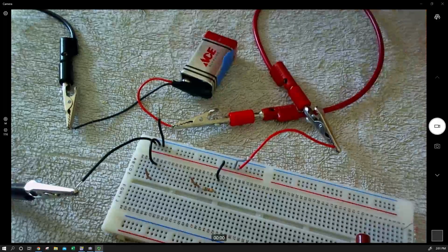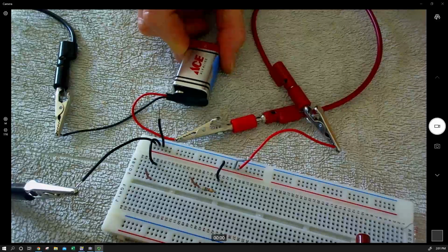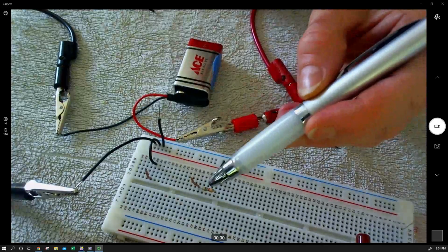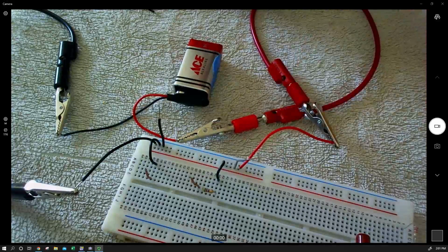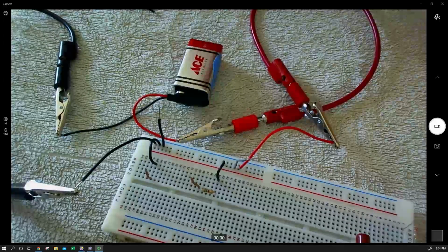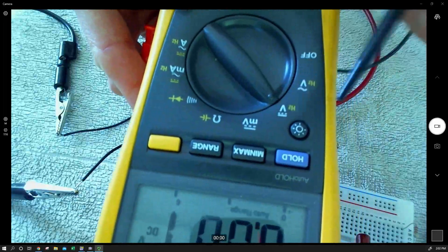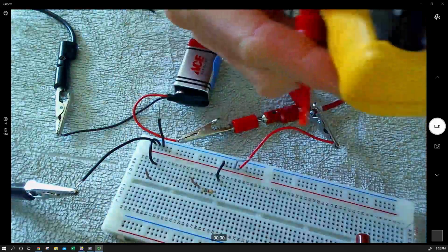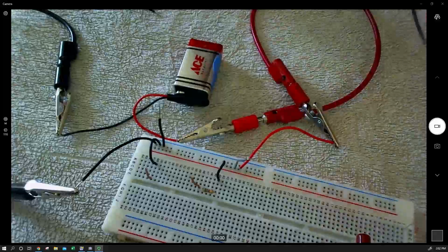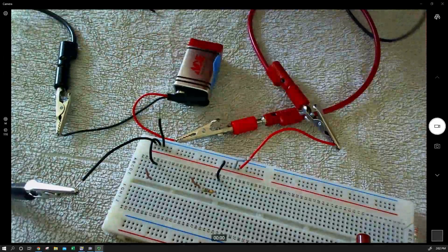So we have, again, a high internal resistance source, single source, driving a high impedance load circuit. And I'm pointing to my 5.56K resistor. So I have my multimeter on volts DC. Remember, using the proper hookup. And I'm going to start by just confirming open circuit.